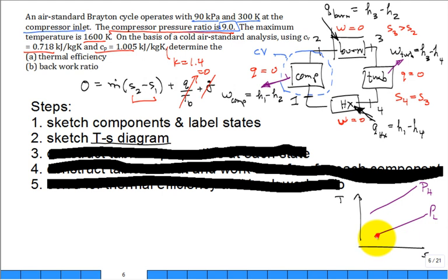We put it through that compressor to get it up to high pressure, state 2, and you do it reversibly. We just talked about S1 is equal to S2. It's isentropic compression. Boom, there you go, there it is. Now you're heating it, so the temperature is going to go up, up, up, until you get up here to temperature T3.